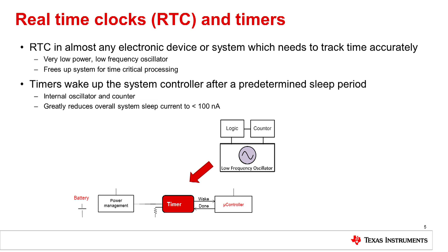This technique allows shutting off the entire system and waking up the controller after a few minutes or hours to perform housekeeping tasks or start normal operation. Sleep current can be dramatically reduced to the nanoamp range. Sleep time is very important in watchdog timers as it also affects current consumption for the entire system.